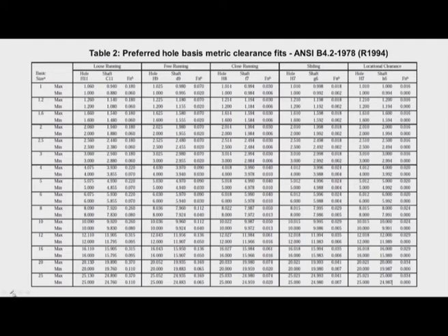So the clearance hole tolerance will be 130 microns. Similarly, depending upon the type of fit required, we can select the locational clearance, sliding clearance, etc.